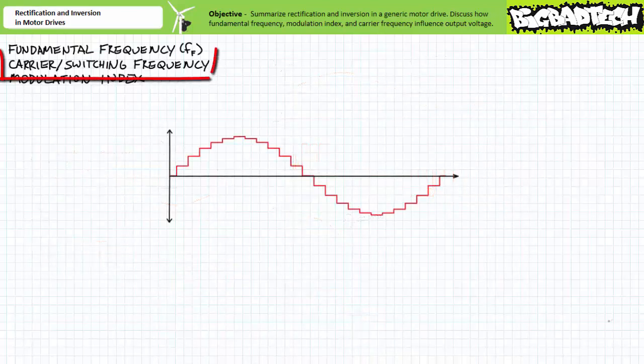The carrier or switching frequency, in contrast, influences the quality of the output waveform. Switching frequency directly influences the number of sections an individual waveform is divided into when approximating its output. For this example, I've chopped a 60 Hz waveform example into 24 different sections, which produces a reasonable approximation of AC. However, if I was to do this at twice the speed, chopping it into 48 sections, it'd be a far better approximation. If I was to continue doing so at geometrically increasing levels of fineness, we'd be hard-pressed to find any distinction between our switched approximation and a true analog continuously variant waveform.